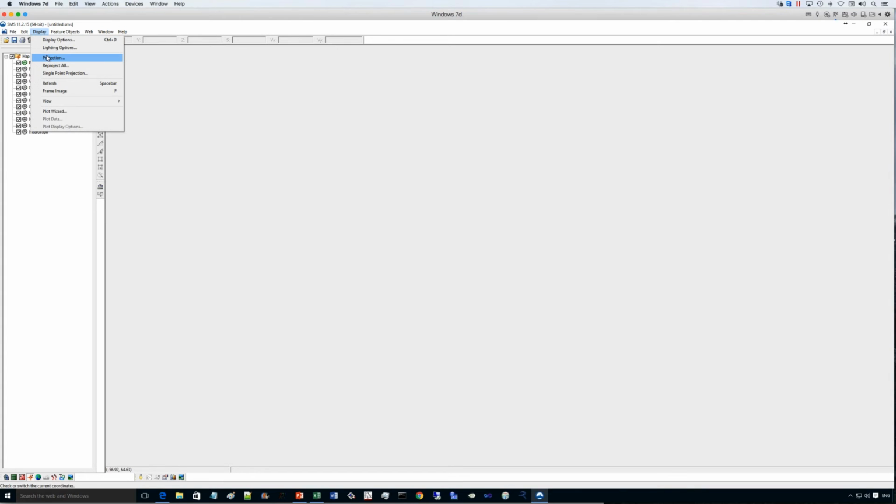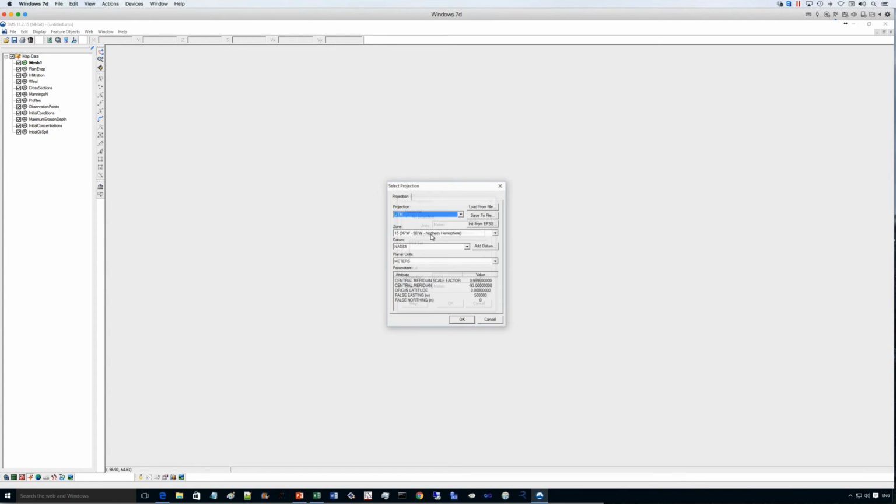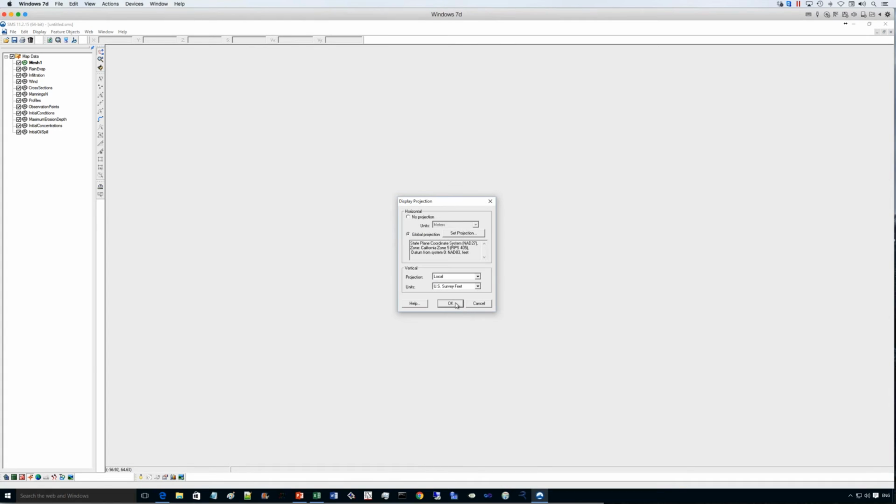Now I'm going to use a projection here because this site is in California, so I'm using a state plane, California Zone 5, and this is important when you try to output the results, especially for Google Earth or some other georeferenced mapping software. And I'm using feet as my system of units here. Okay, so I have my basic RiverFlow2D environment created.